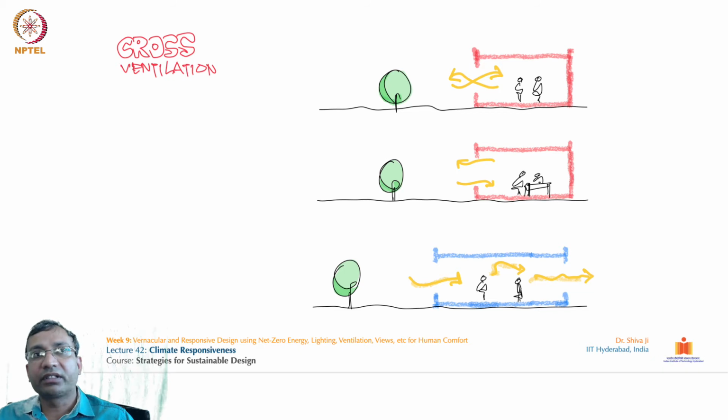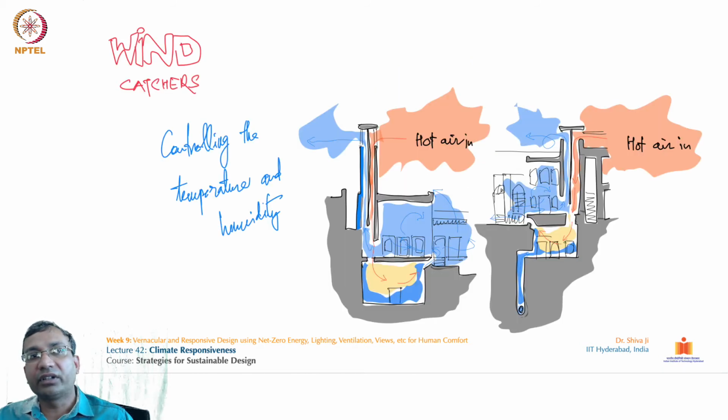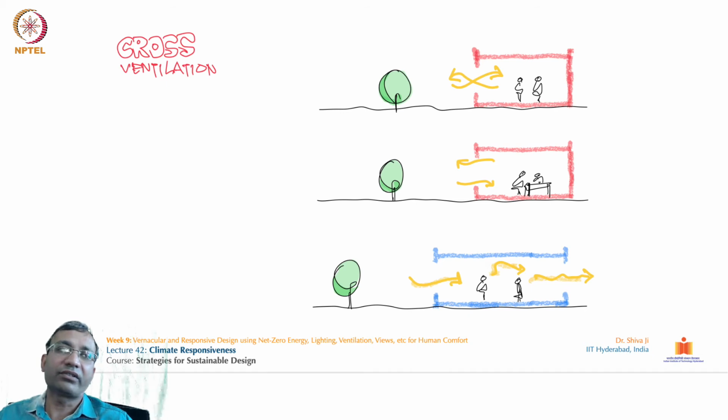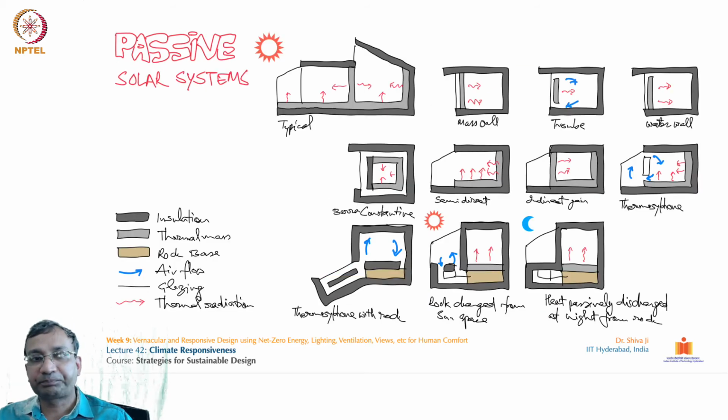Continuing our previous discussion, in the cross section also we can plan our openings in such a way, like the one we saw in this wind tunnel, wind breeze wall cross section. Even if we are not going to have very tall structures, we can plan the openings, the cross section of these openings, the length and width of these openings, and make them vary. Depending upon that we can control the passage of wind through the premises.